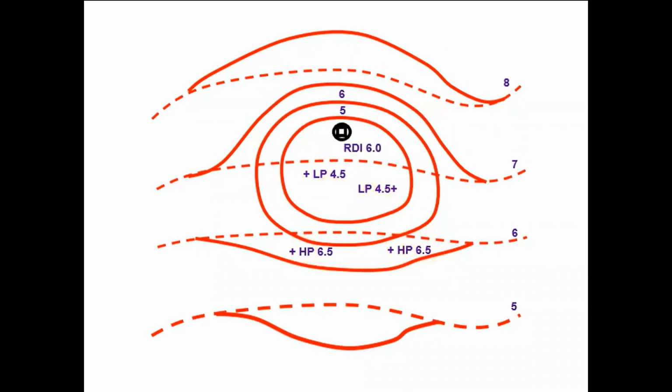So the way we control the depth of the water sitting in the retention system is with a raised drop inlet. And you'll notice that this raised drop inlet is half a foot below the high points on the berm. That's important. You have to maintain that half a foot below.